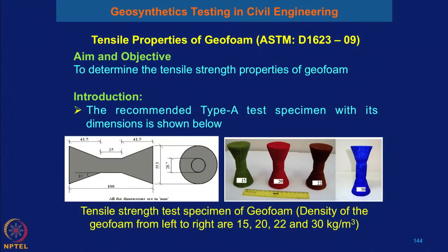So far we have discussed the compressive strength of the EPS geoform, and now we will discuss the tensile properties of the EPS geoform, and this is as per ASTM D1623-09. Here the main objective of this test is to determine the tensile strength property of the EPS geoform.